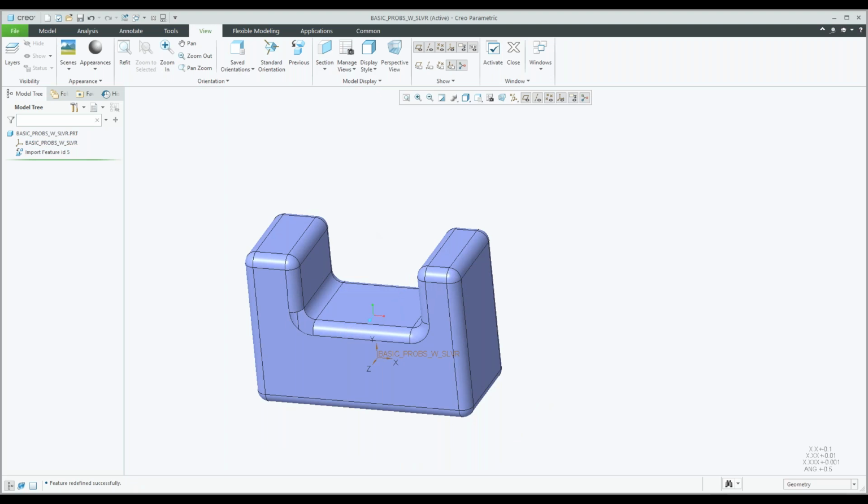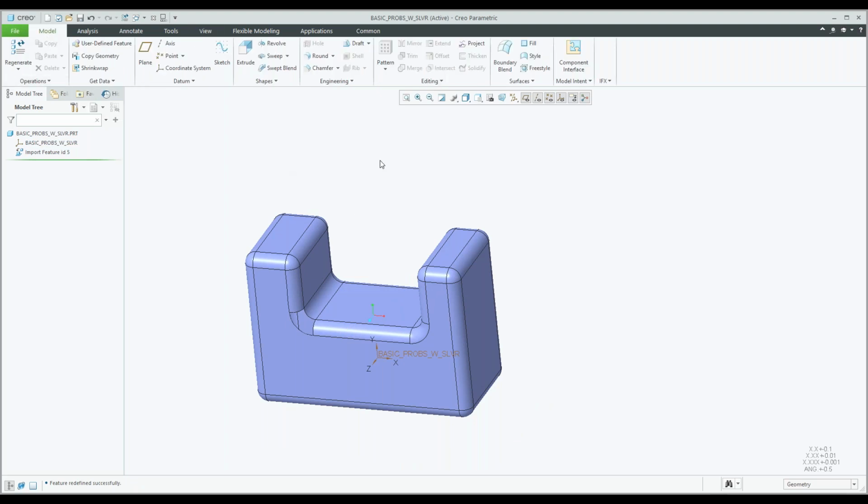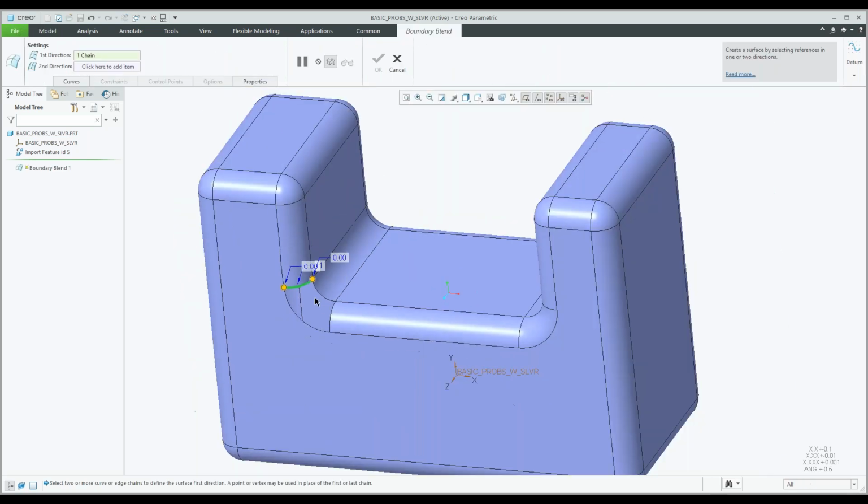Then you can create surfaces and features outside of import data doctor, and then just use the collapse functionality. So if there wasn't a full option in the import data doctor, and I couldn't use style or any of the other surfacing tools, you can use them, and then just collapse that into the import geometry. And that's going to give you the same result. So let's quickly do that.